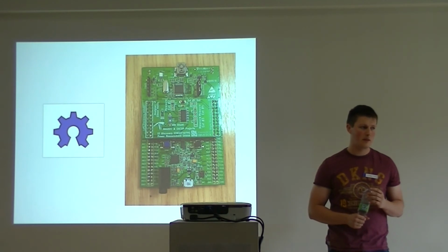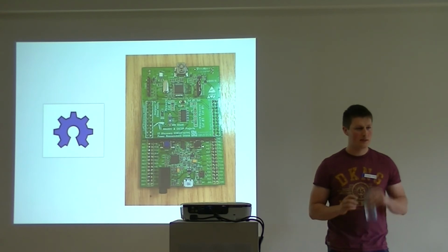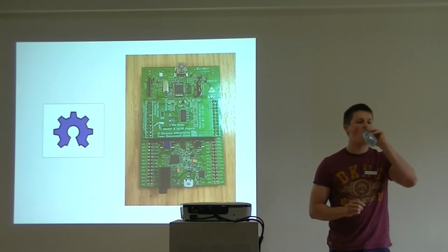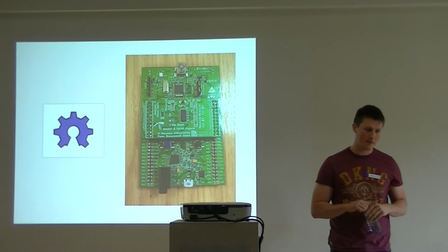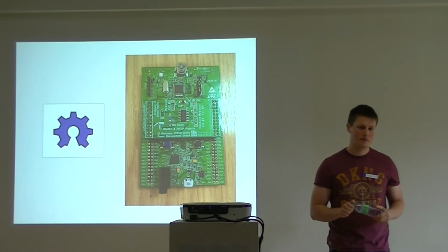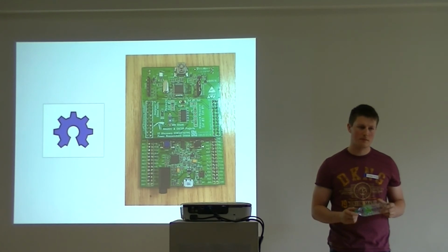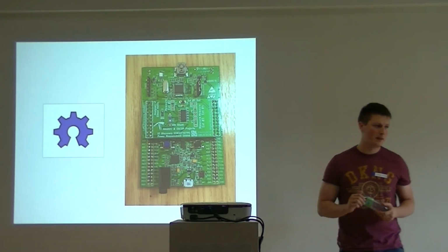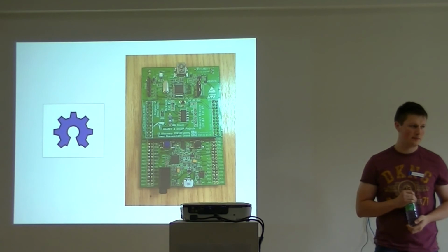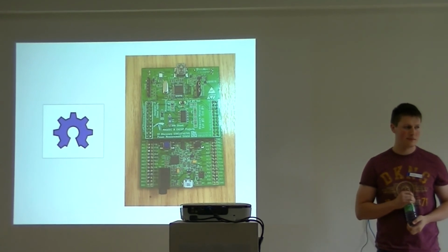That sounds perfect for my project. I'm guessing most of the time you don't actually need that high dynamic range, because if it's right down at microamps, then the total amount of energy consumed for however long, you can measure that separately. I mean, the main concern when you're building these kind of things is to make sure that the damn thing's asleep when it's supposed to be asleep.